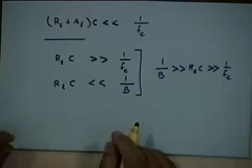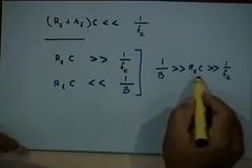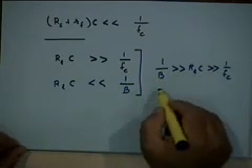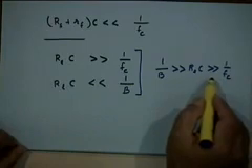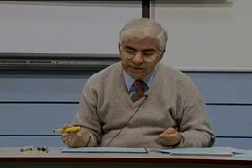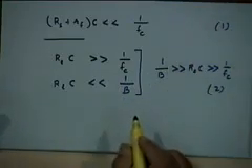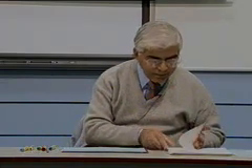The time constant R sub L times C should be much less than 1 by B, but should be much greater than 1 by FC. So if these two conditions are satisfied, by and large you will have a system which works nicely, right? So these are the two conditions that we need to satisfy. Any questions?